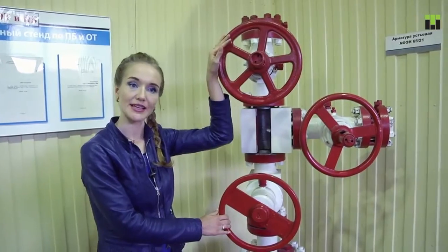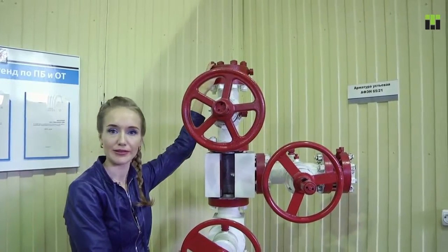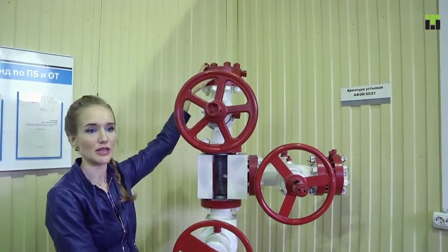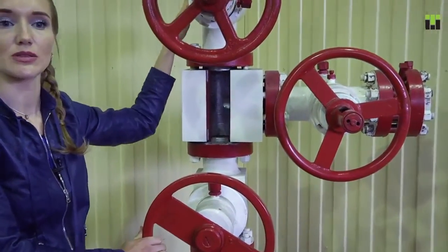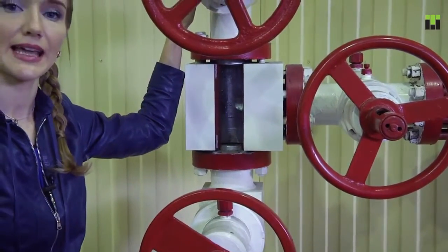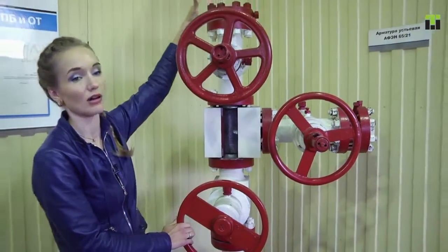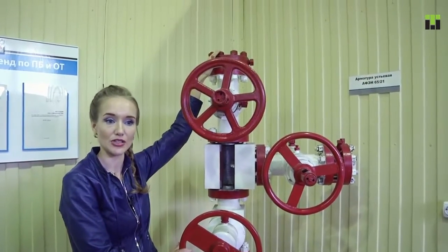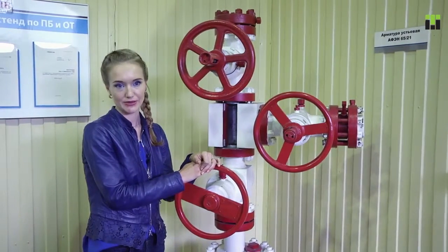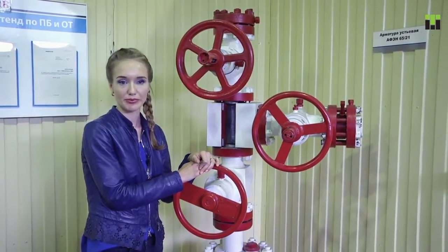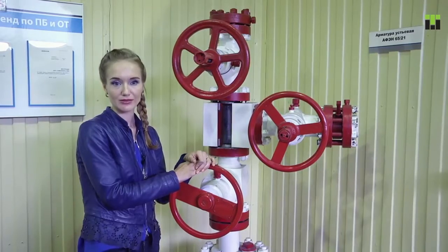In such cases, a lubricator is installed on top and the required tool, a paraffin scraper for example, is lowered into the wellbore on a wire. Thanks to the lubricator, the well remains leak-proof and can operate while the tool is working. Manometers are installed on the Christmas tree for production control purposes. Different types of Christmas trees have different characteristics, such as design, operating pressure, flow diameter, number of flow strings attached, types of valves, and chokes.